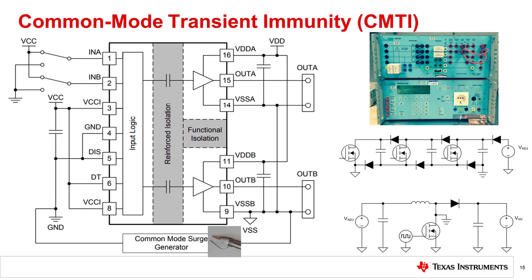Since bandwidth and rise time are inversely correlated, fast probes and a high-speed oscilloscope are required to measure fast transients. The probe voltage rating must also be considered for higher voltages. Finally, the output state must be monitored for changes.